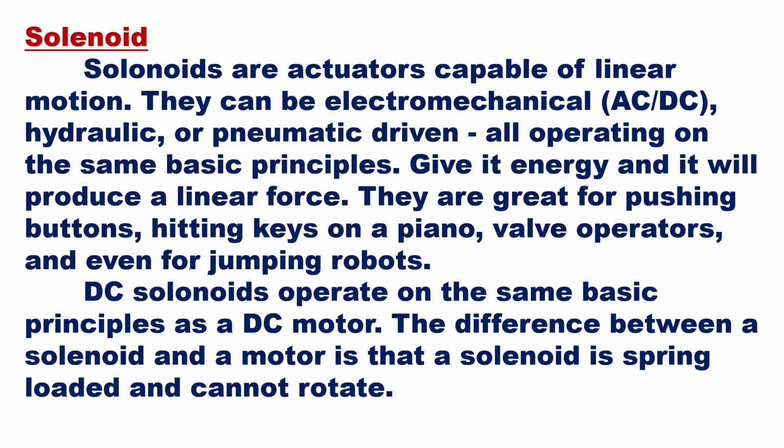Give it energy and it will produce a linear force. They are great for pushing buttons, hitting keys on a piano, valve operators, and even for jumping robots. DC solenoids operate on the same basic principles as a DC motor. The difference between a solenoid and a motor is that the solenoid is spring loaded and cannot rotate, so it will give you a linear motion.